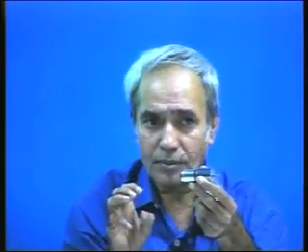Mostly we use what are known as permanent magnet motors. In the past, the permanent magnets were not very powerful. You don't get much torque from them. Today, we use what are known as rare earth magnets, and they deliver powerful magnetic fields. Consequently, for a given size with a rare earth magnet, you get more torque than with the conventional magnet. We don't use electromagnets in the field coils because they will absorb energy. Okay, so that's the problem with the electromagnet. It will absorb some amount of energy.